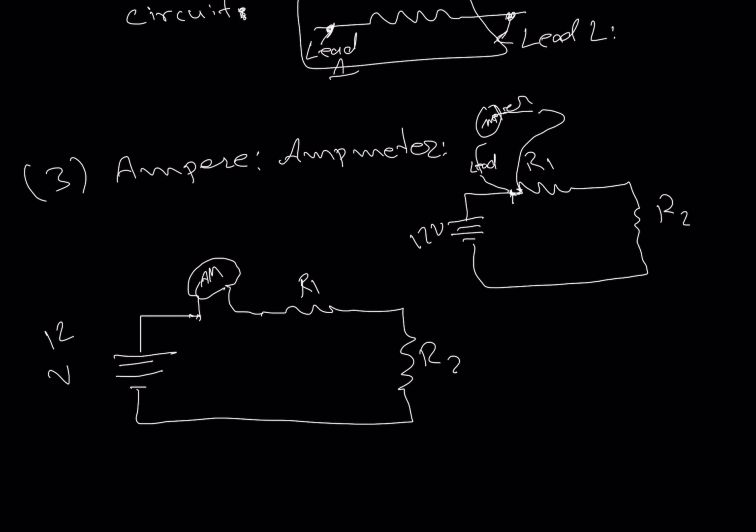So if we figure that out, and if our operation is safe to be used, then we can connect one lead. The power should be coming from there, connect that to the power, or you can even connect it right here too, or anywhere you want to, because it's a series connection, so your amperage should be the same here. One lead is coming from the source, and the other one is going to the resistance. It will tell you how much amperage is going through that circuit.